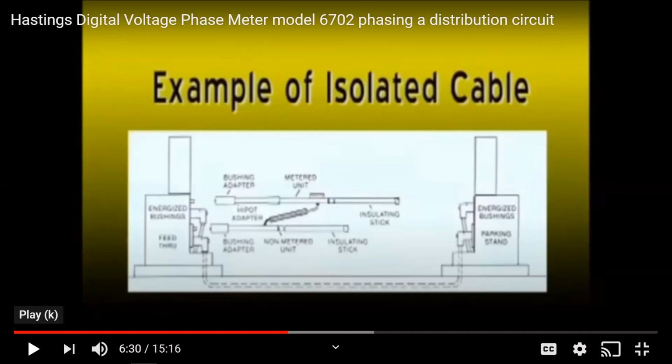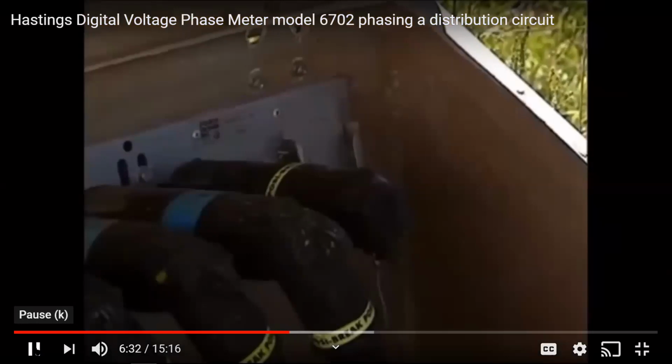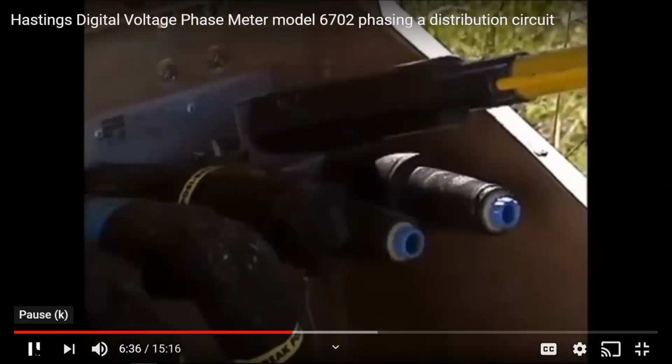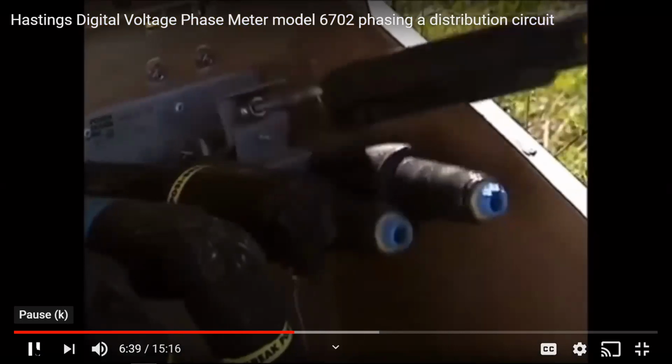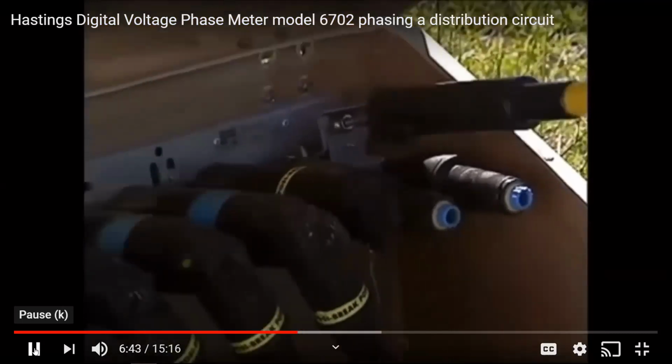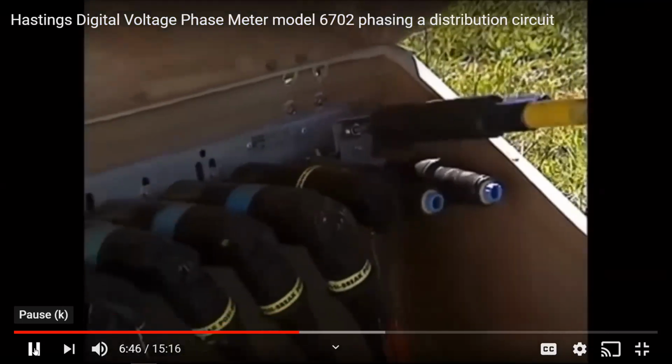That's a dead end. And stop. You definitely cannot leave it on the transformer, because if you do, it's just going to test cable on and on and on. And this stick does not work through transformers. So you can't use this testing the actual transformer core itself. It's going to give you a bad reading. We've got three cables that show a variety of faults on them. And so we're going to show what happens with each of the different conditions.